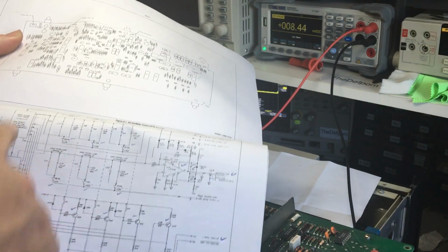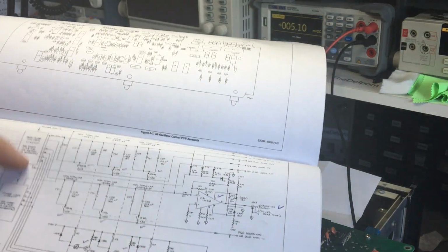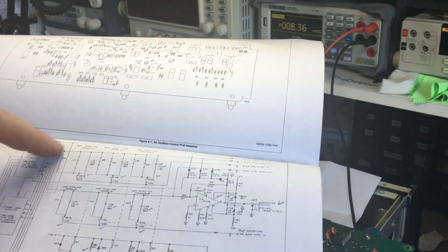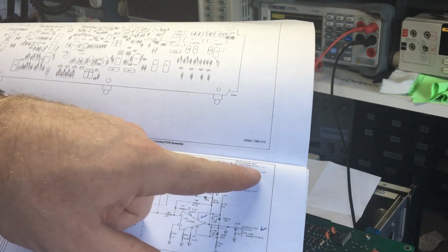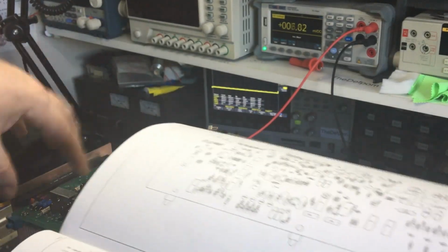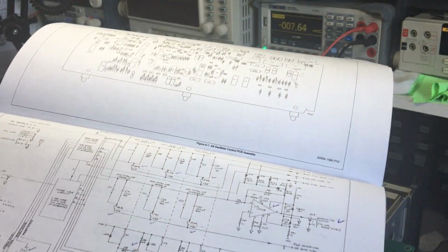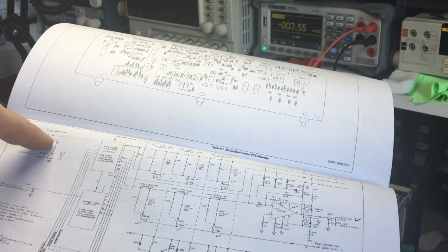So I'm looking now at these two circuits. I'm going to look at the amplitude control circuit first, because, well, actually they both link into the summing amplifier input, which is a signal which is missing off the other board, the oscillator board. There's no signal there, so I think it should be passing through here, because oscillator control in is over here as well.